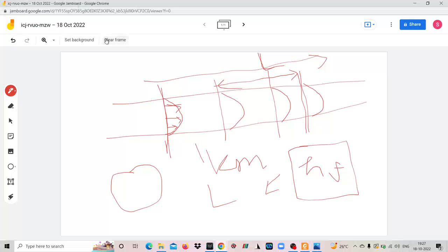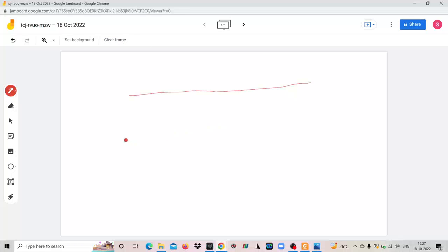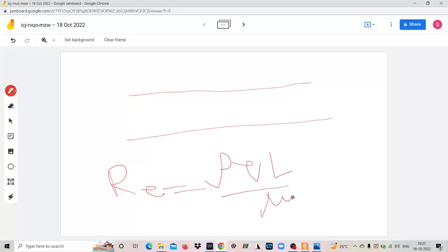Suppose our intention is to study only fully developed flow. See, what is the definition of Reynolds number? Definition of Reynolds number is rho v L by mu, right? What is this L here? This L is the characteristic length. Suppose you want to study this pipeline, say only for its length L1, not the entire length. So for that your Reynolds number will be rho v L1 by mu.